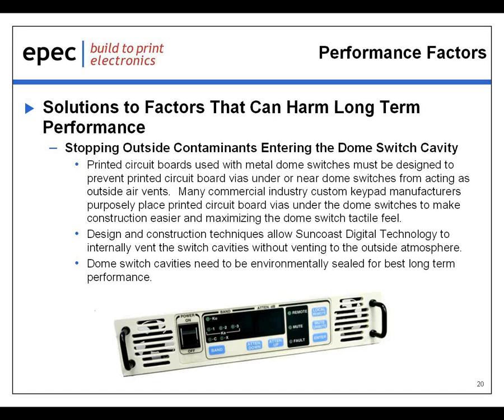However, venting the switch is a very big problem because it allows outside contaminants to enter the switch cavity and create non-conductive switch surfaces. Our design and construction techniques at Suncoast Digital Technology prevent the dome switches from breathing external air in and out of the dome cavity by venting the air around within the assembly but not going outside. Now, obviously, dome switch cavities need to be environmentally sealed for the best long-term performance.